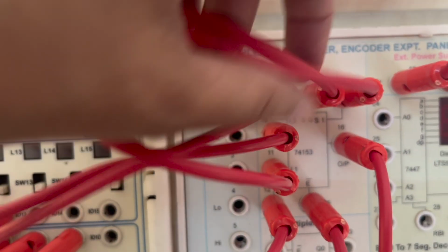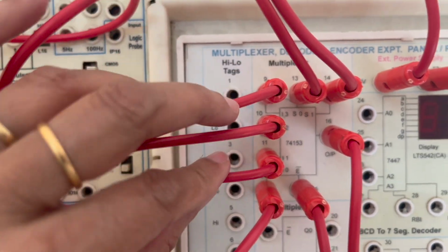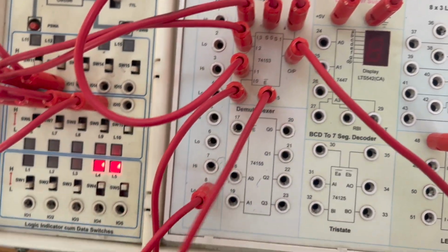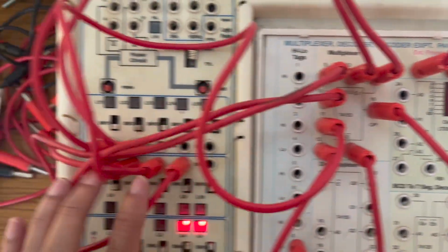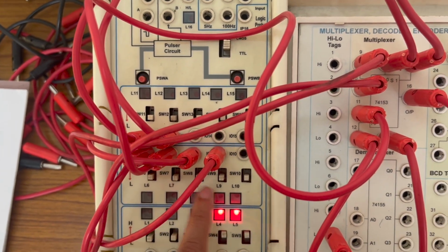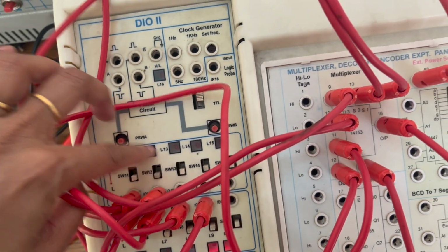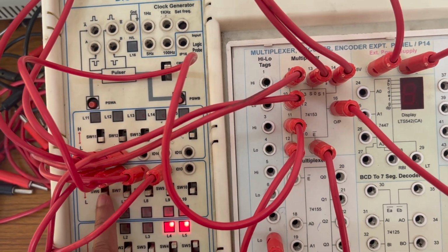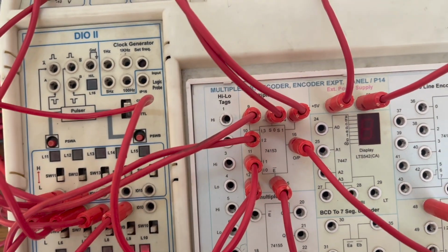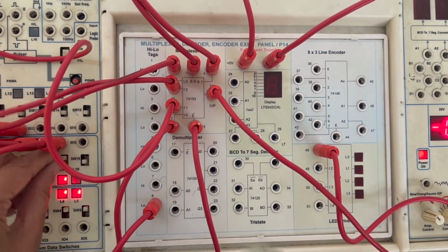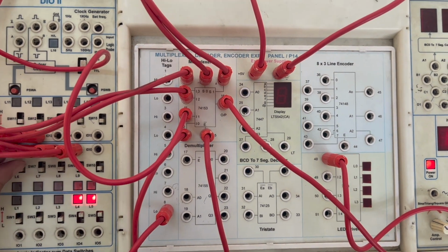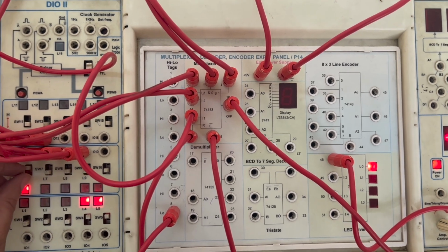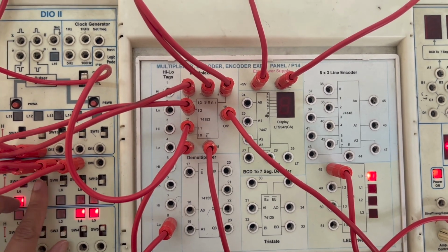4x1 multiplexer circuit. So we'll have 4 inputs, 2 selection lines and 1 output, right? One output is connected to LED. Then 4 inputs are connected to switches as well as 2 selection lines are connected to switches. All the switches are at low position. You can observe, right? All the inputs are at low position. The selection lines are also at low position, and so output is low. 0, 0, first output is selected. See, it is responding to first switch. It's not responding to other switches because the selection line is 0, 0.